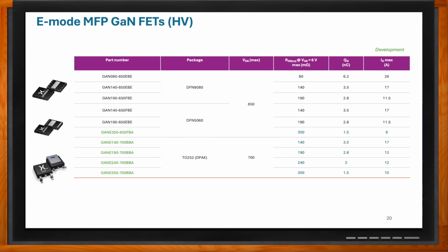That part can be turned on at 1.5 volts versus 4 volts for the D-mode. Same thing goes for the turn-off. The gate is so sensitive that the layout has to be extremely sensitive as well. Everything has to be placed just so, with not much room for a mistake. A lot of noise can enter the gate because it's not noise protected for the E-mode, but you can drive it at much higher frequencies, though at lower power.